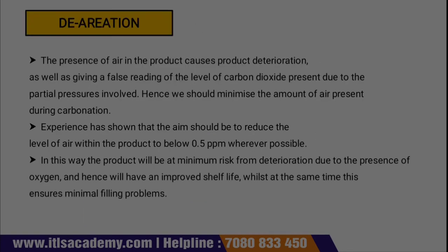Then comes the deaeration. The presence of air in the product causes the product deterioration as well as giving a false reading of a level of CO2 present due to the partial pressure involved. Hence, we should minimize the amount of air present during carbonation.